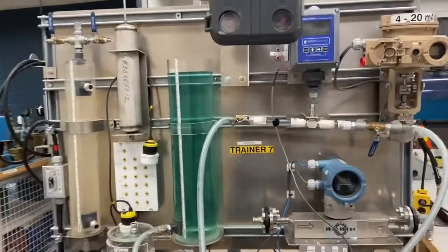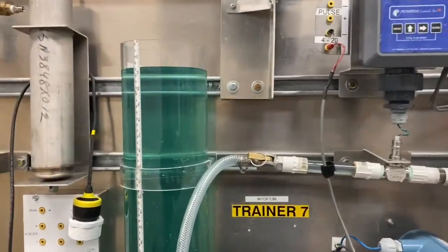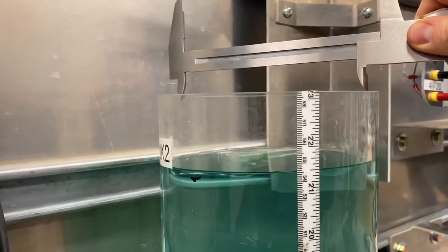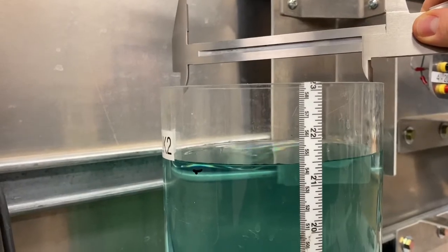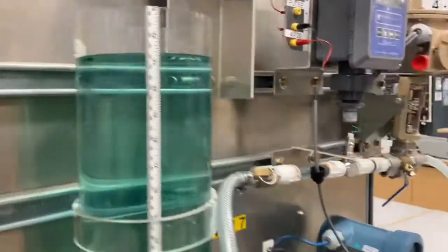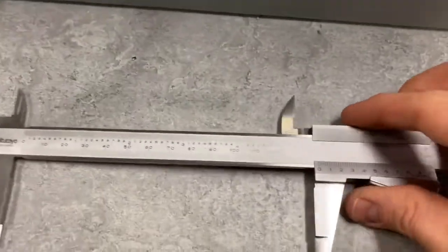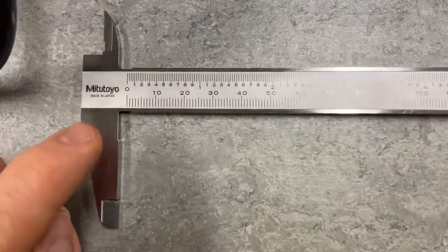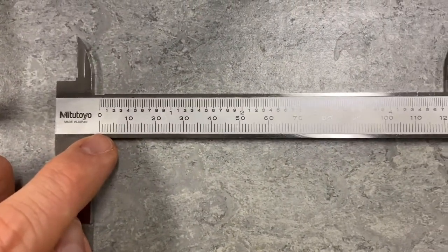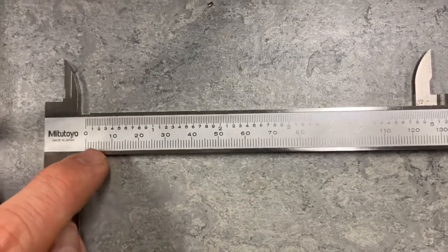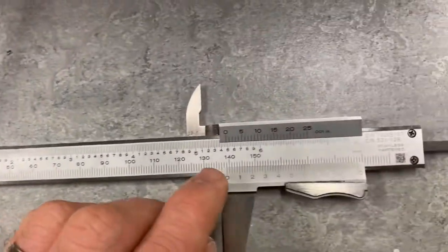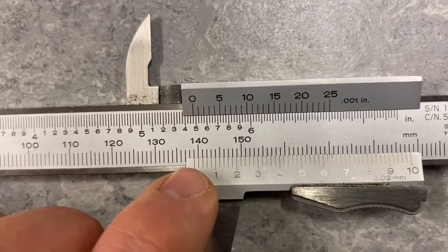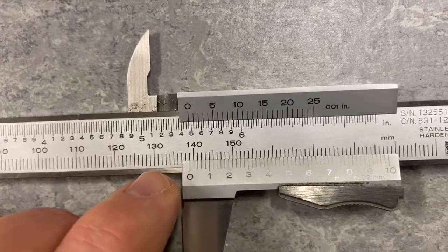One last thing here, I believe in the lab procedure there's a P&ID with the inside diameter of this vessel, but just to prove that it's correct here, I used a vernier caliper and I've put it in here already and got this measurement. And so we'll just show you the inside diameter here for proof. So you can see 0 right here. 0, if we slid this all the way over, would line up with the 0 line right here. So we're going to the nearest millimeter, and this is all in millimeters on the bottom here. So 0, we go up to 130, and then the 0 line lines up with the 9th division there between 130 and 140. So 139 millimeters.